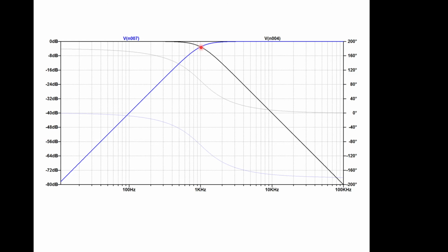I think it's a fourth order one we designed there just to make it interesting. So you just have to remember that a fourth order filter will be just two second order stages cascaded, so you get to do the calculations twice, just for some practice.